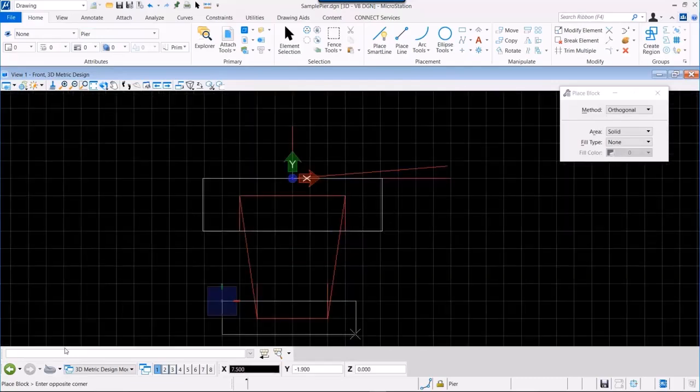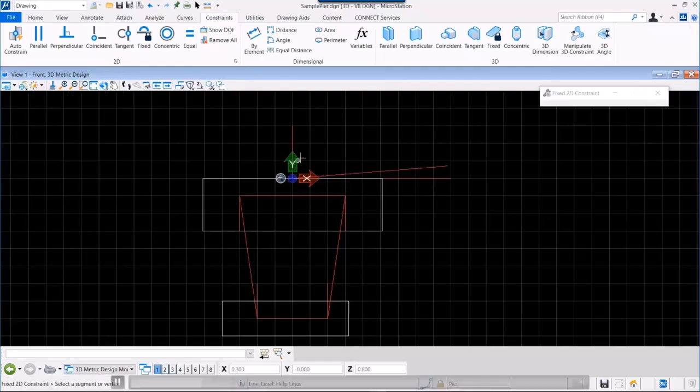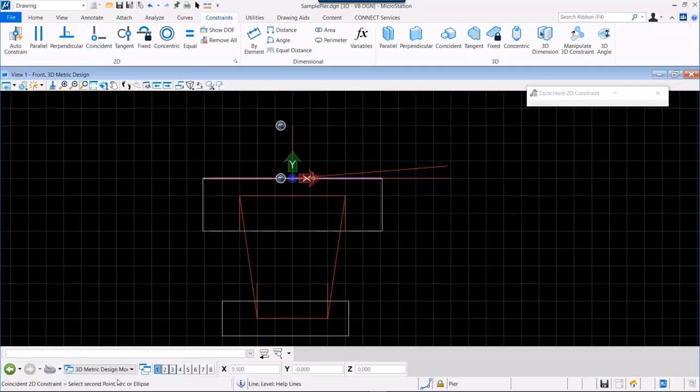As you can see, I'm not attaching any dimensions or perfectly drawing the dimensions, because I'm going to adjust this with variables. Then the next step is to start constraining this. And then again, we have different constraints, right? So for example, I'm saying here that this coordinate system, let's call it like that, is fixed, so it's not going to move. And this is going to be the placement of the working point, some people call it like that too, of when I place my abutment.